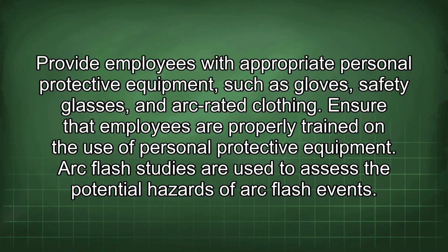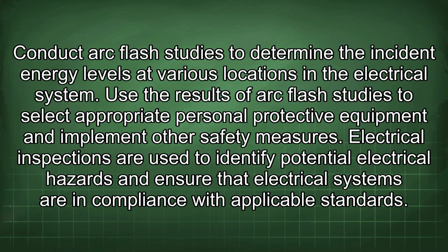Arc flash studies are used to assess the potential hazards of arc flash events. Conduct arc flash studies to determine the incident energy levels at various locations in the electrical system. Use the results of arc flash studies to select appropriate personal protective equipment and implement other safety measures.